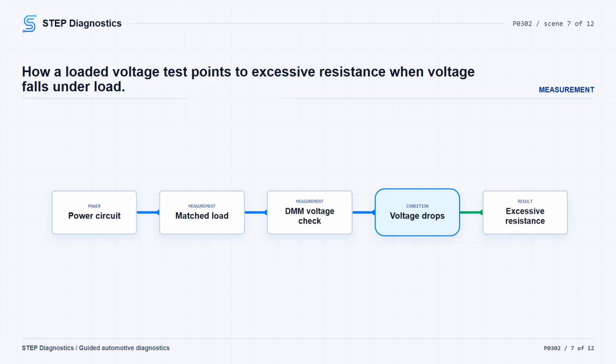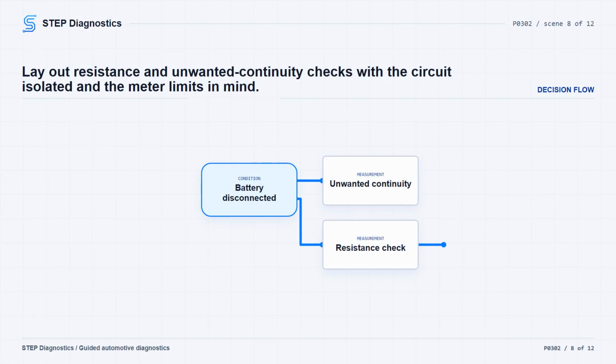When checking resistance or continuity, expect less than 2 ohms for most small diameter 18 gauge and smaller wires, and expect less than 2 ohms of resistance for most wiring harness circuits. Keep the meter's limits in mind too. A standard DMM ohm meter's low resistance resolution, approximately 0.1 ohm, limits its accurate use to circuits carrying less than approximately 5 amperes.